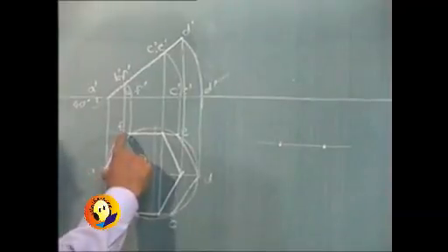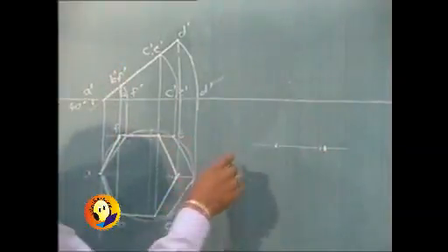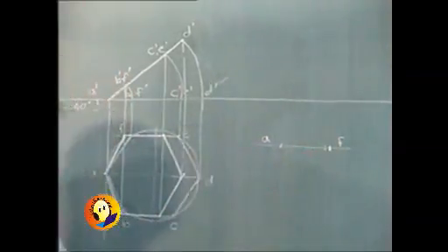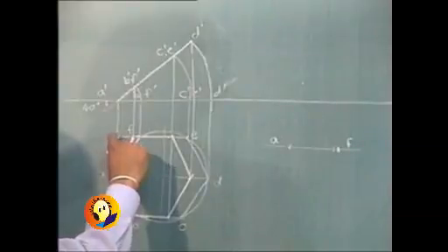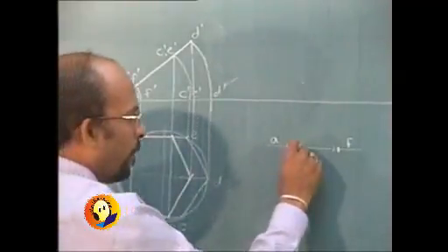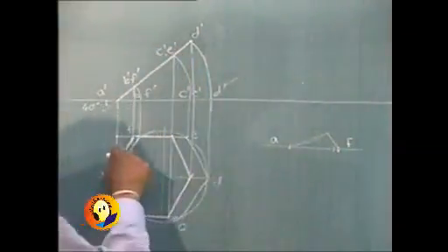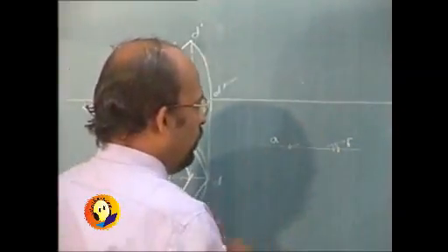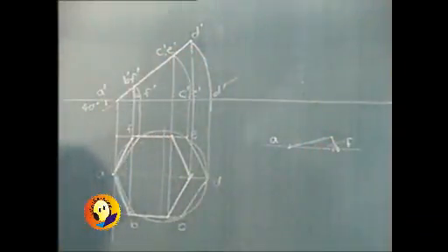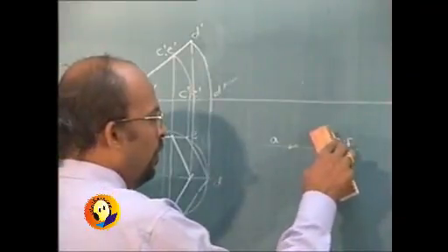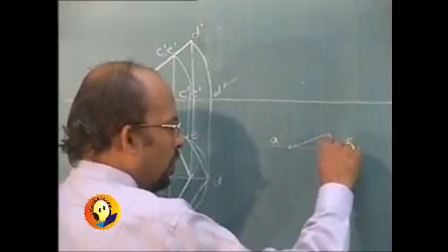With this AF side, which is marked over here, if we are to reconstruct the entire plan, the best way will be to first of all get this corner, so that if you can get this right angle triangle from here at this position, then the job will be simpler, because we can now construct the rectangle of these sides.